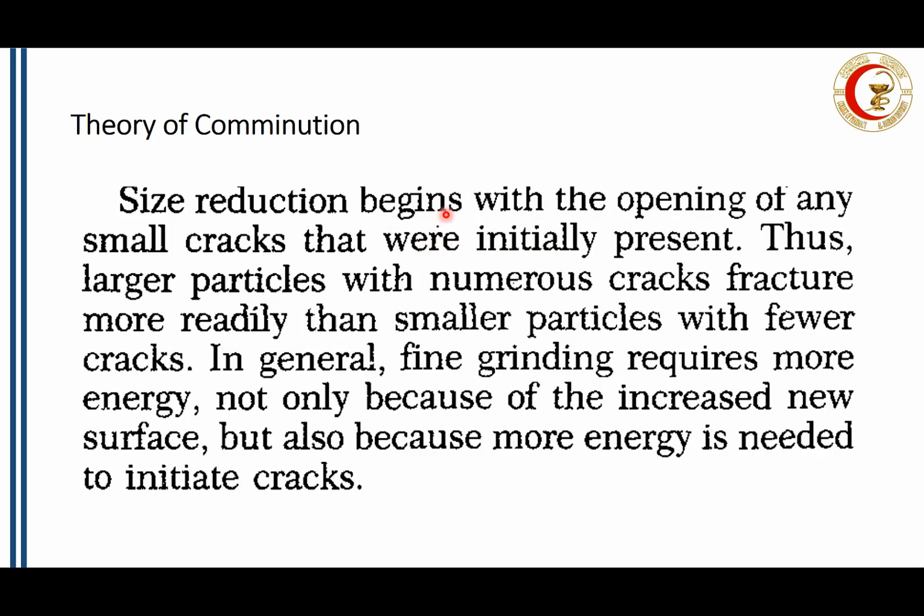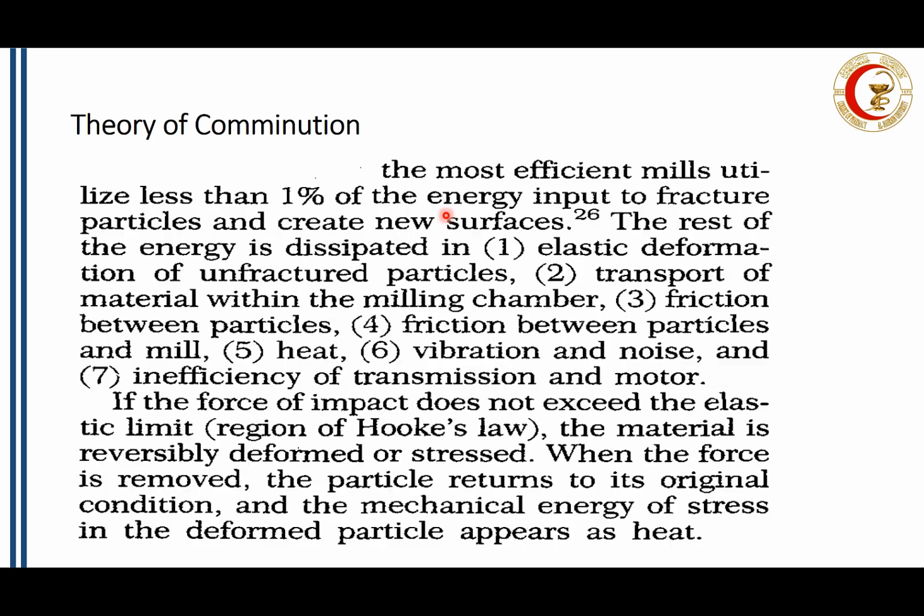Now, size reduction begins by opening of small cracks that were initially present. Thus, if we have larger particles with more cracks in them, they will be easily reduced to a smaller particle size than small particles with fewer cracks or fractures in them. Why? Because we will need more energy to initiate new cracks in these small particles and break them into even smaller particles.